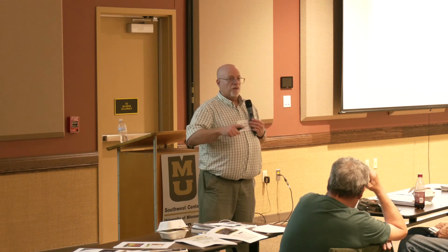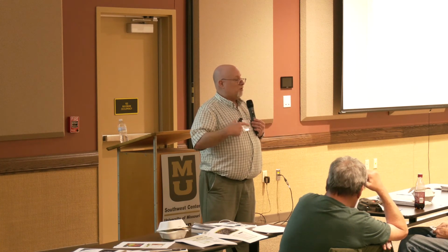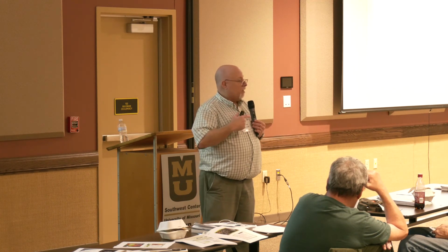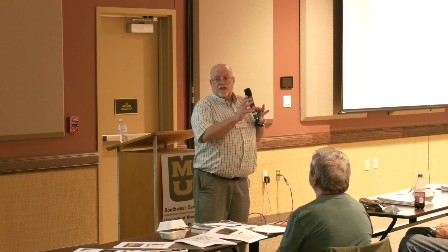The systems can be automated so you don't have to worry about it, but you still should double check them. Like Dr. Snyder said, worry, check. That's the only way you're going to know there's not an issue out there. If I'm on a more clay or loamy soil, I may be able to do it every other day, but chances are drip systems are designed to operate daily. That's their function. And if you try to make up by just letting it run for 8, 10, 12 hours or overnight, you end up super saturating part of the soil and you lose most of that water to gravity. It just keeps going down. You don't get good lateral movement across the beds. That's what this is supposed to do.